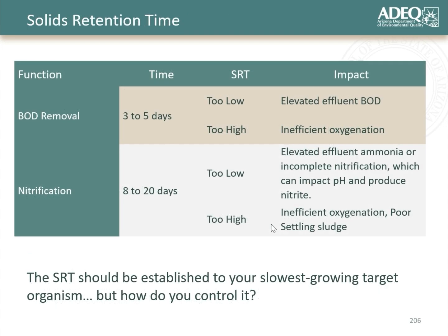Going back to the solids retention time, though, there's a couple rules of thumb that we have. For BOD removal, typically a 3 to 5 day retention time is all that's needed for BOD removal to occur, to allow enough time for the heterotrophic bacteria to do complete BOD oxidation.